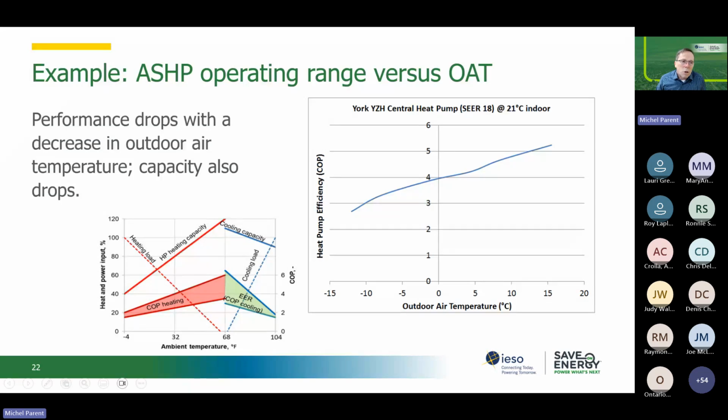If you look at the graph at the bottom here, you will see that you can actually kind of predict your heating load. Heating load for a building will typically vary fairly linearly. So will the cooling load, and those are approximate. And you can actually have a crossover point where your heat pump will no longer be able to provide you enough heating.